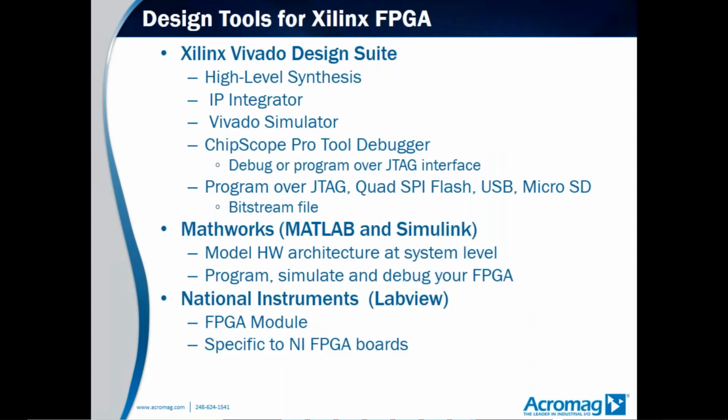As I mentioned, the design tools for Xilinx FPGAs: Xilinx has the Vivado design suite. They have a high-level synthesis tool, an IP (intellectual property) integrator, what they call their Vivado simulator, and then they use the ChipScope Pro Tool debugger. This debugger allows you to debug or program over a JTAG interface, and you can check out timing, check out code, that sort of thing with this ChipScope debugger.